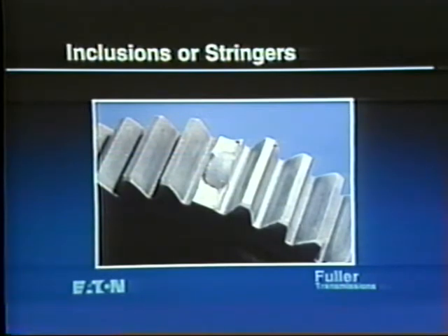Remember, as with all fractures, inspect the transmission's gearing, bearings, shafts, keys and keyways, and case for possible damage.